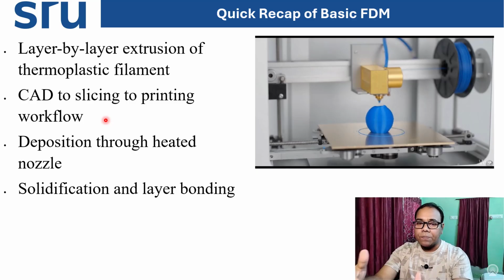So this flow has to be maintained. First CAD designing, after that you have to save your CAD model into the STL file format. Why STL file format? That we have already discussed, because the machine which will print this requires only information about how the print head should be moving, or maybe the stages should be moving, in the X direction, Y direction and Z direction. So the G code, M code, and X, Y and Z coordinate variation is required by the machine.